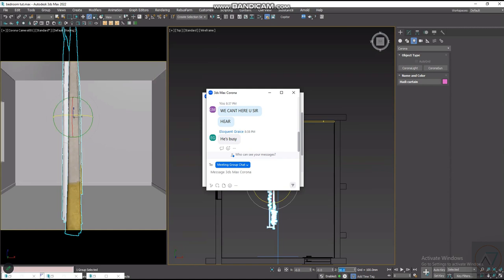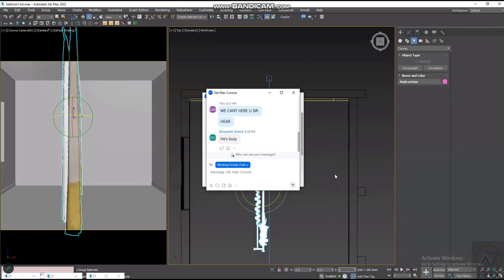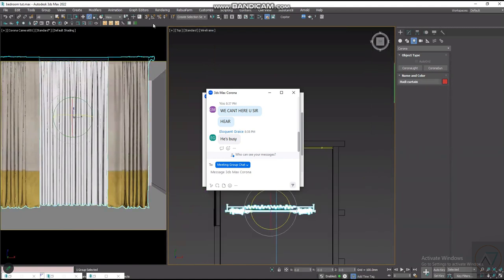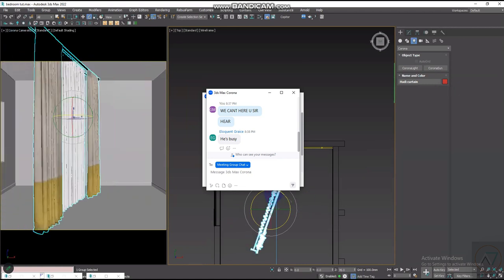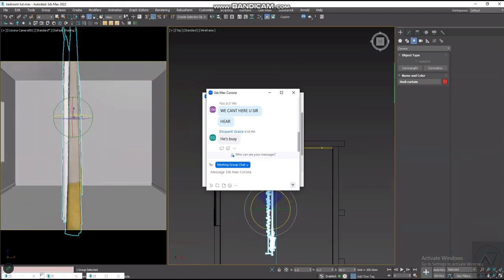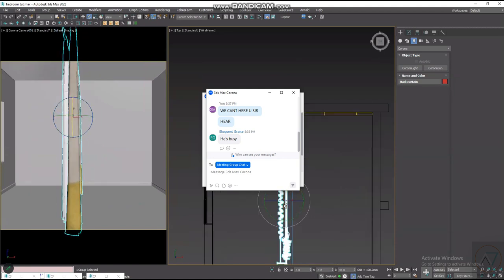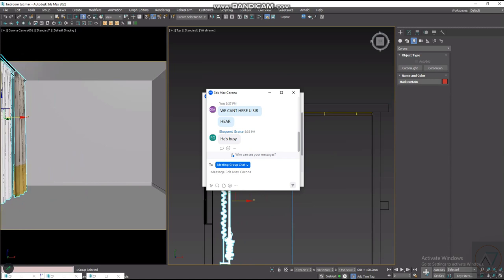I enjoy using the gizmo to rotate, so I'm going to show you that now. Let me set it back to 0. For you to cancel out the random numbers, you have to toggle on this snap, this one here. Now if I use the rotate, you can see it's giving me reasonable numbers, 85, 90. We want 90. Then change to move, W to move.